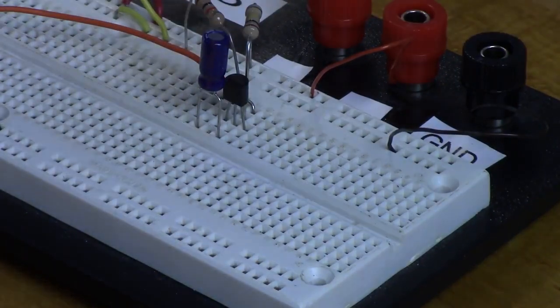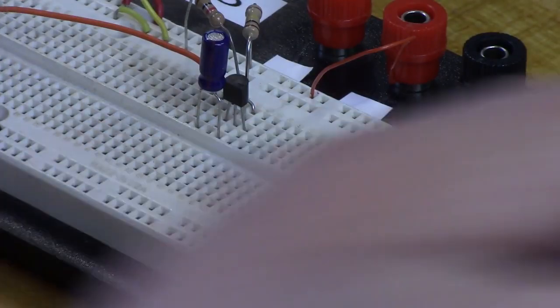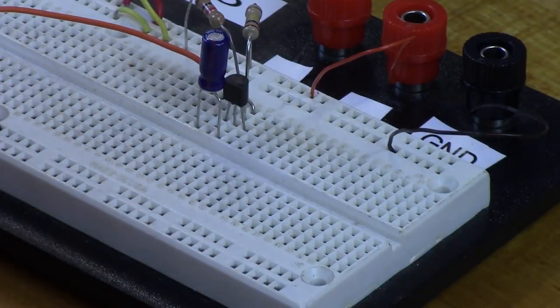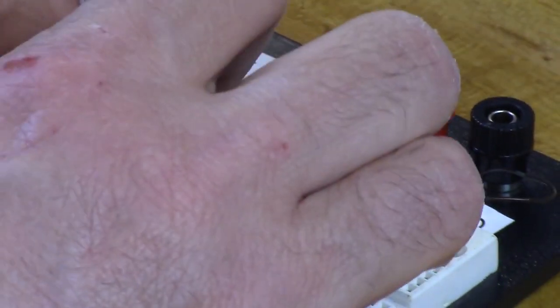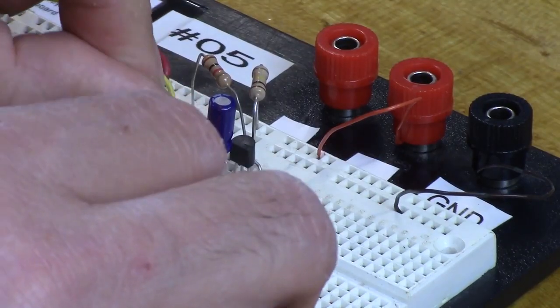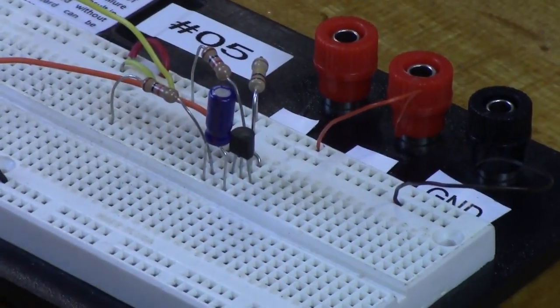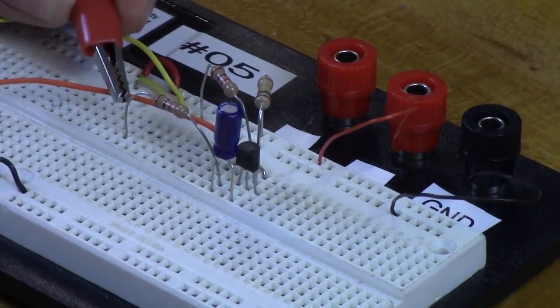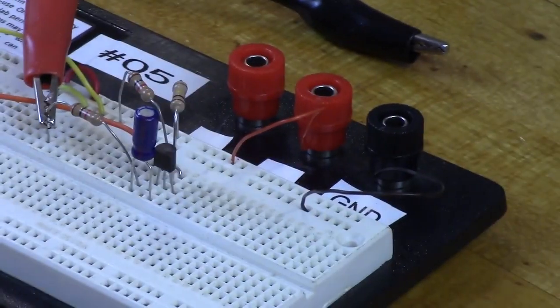And then from there, we're going to go through our RS, which is a 1K resistor, which is this guy right here, going off to the side. And that is where we're going to connect our signal generator. So we have our coaxial cable with the alligator clips. The red is going to connect to the input side of RS. The black is going to connect to ground, which I'll put in a minute.